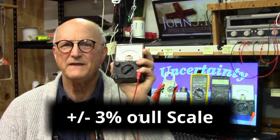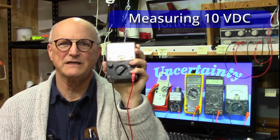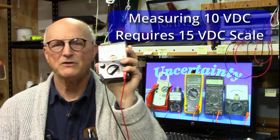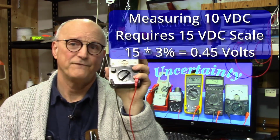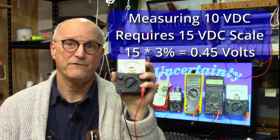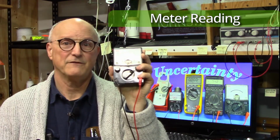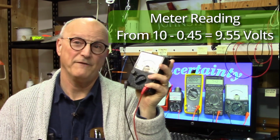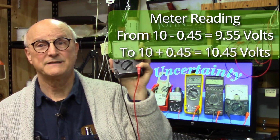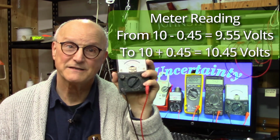Well, what this means is that if I have my meter connected to a perfect 10-volt DC battery, I would have to use the 15-volt scale. 3% of 15 volts is 0.45 volts. So in reading this perfect 10-volt DC, I could read anything from 9.55 volts to 10.45 volts and still be within its tolerance.